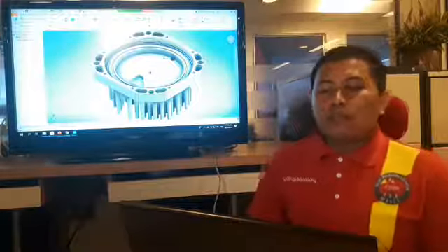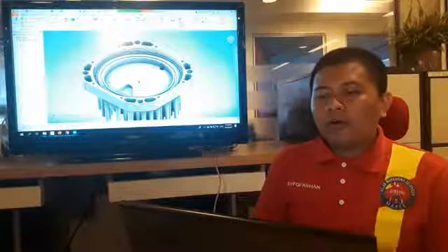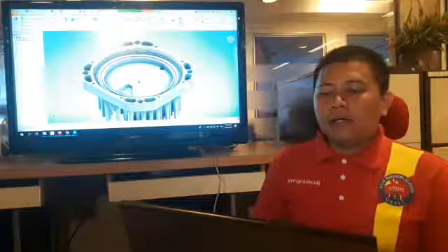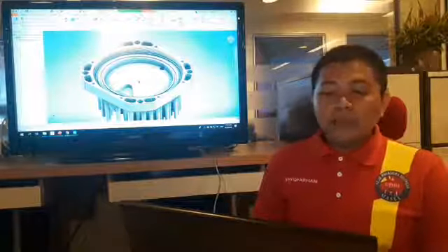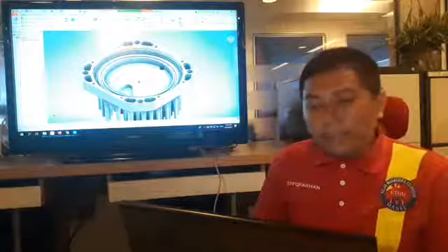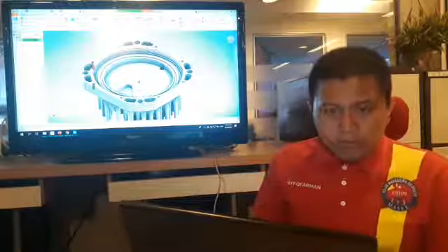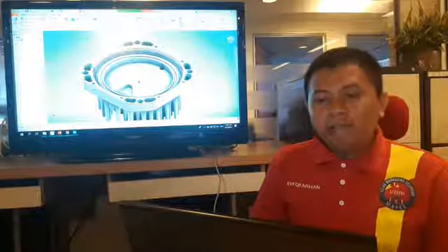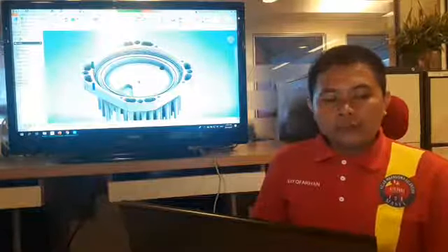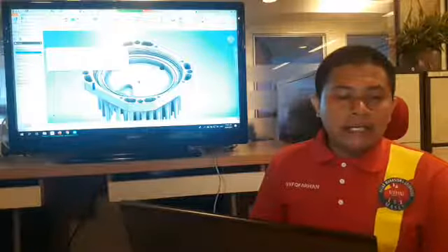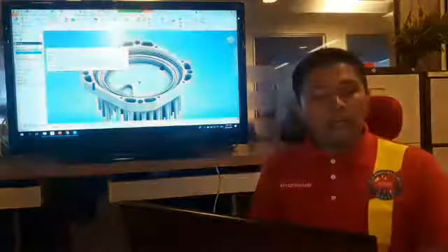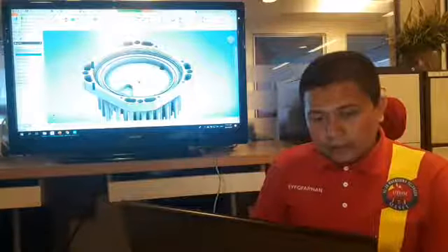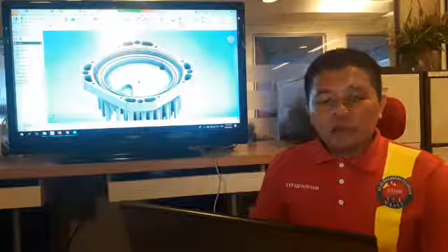Right. So as you can see, there will be 4 sides. If the circle over here is a circular pattern, you can simply use a pattern for this job. You just simply click on the pattern. Okay, so you can choose either a linear pattern, circular pattern, mirror, or duplication. So for example, for this case, I want to choose a circular pattern, so I just simply choose the circular pattern, and I need to choose the axis.